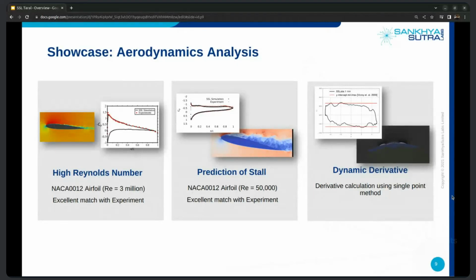Any solver can be judged by the ability to capture fundamental flow phenomena. Of relevance to aerospace and automotive flows, you can think of this as capturing free transition of boundary layers, or separated flows where you have very large pressure gradients, or even bluff bodies, and cases like dynamic stall. When you use wall models or other treatments, or you use modeling to capture scales that you're not actually resolving, your simulation might give you incorrect results altogether, because it's not suitable to the application that you're trying to use it for at all.